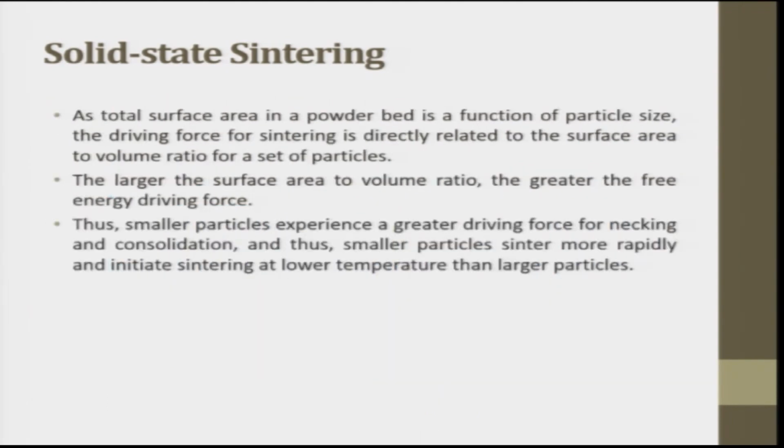As total surface area in a powder bed is a function of particle size, the driving force for sintering is directly related to the surface area to volume ratio. This is nothing but S by V. Okay. The total surface energy is related to the S by V ratio of the particles. So, particle size and volume, aspect ratio plays a role. The larger the surface area to volume ratio, the greater the free energy driving force. So, if the particle size is smaller and smaller, nanoparticles, the volume will be very small, surface area is very high.